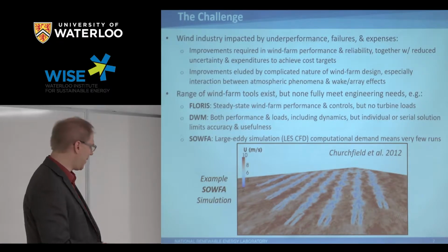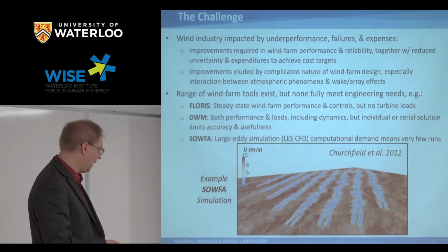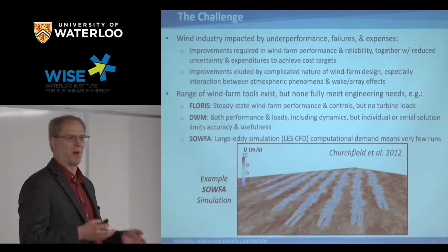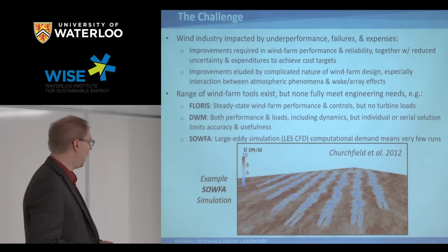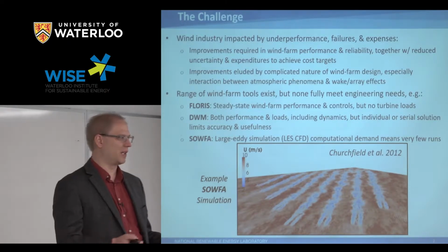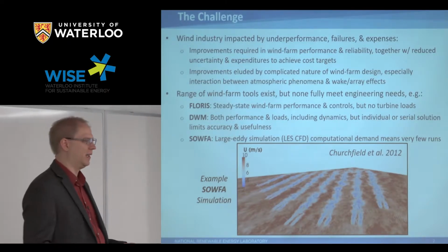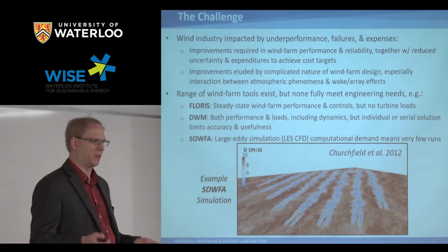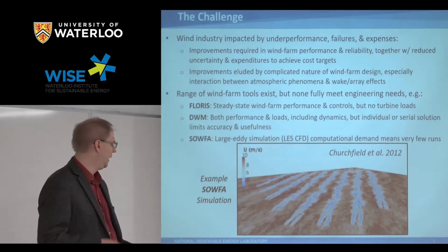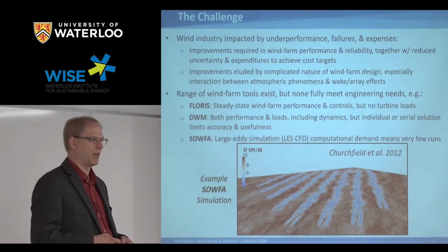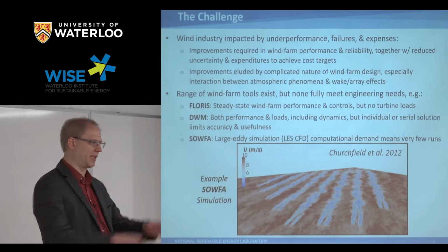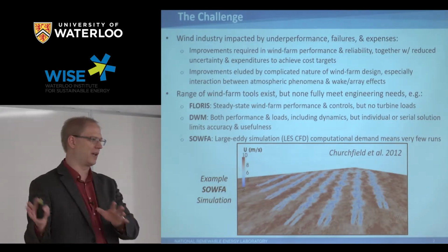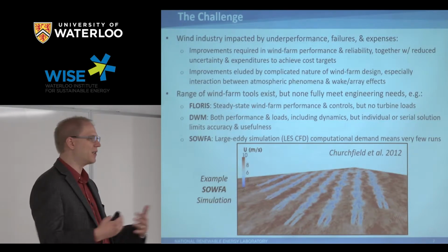And so while you may sacrifice a bit on the upstream turbine, you'll get more than that back on the next turbine. So by using things like wake steering, we can improve the overall energy efficiency of a wind farm by basically doing nothing. We've shown this both in simulation and also in prototype tests where we take a corner of a full wind farm and start applying these wake steering technologies, and clearly, relative to the rest of the wind farm where we're not doing this, the energy is going up.